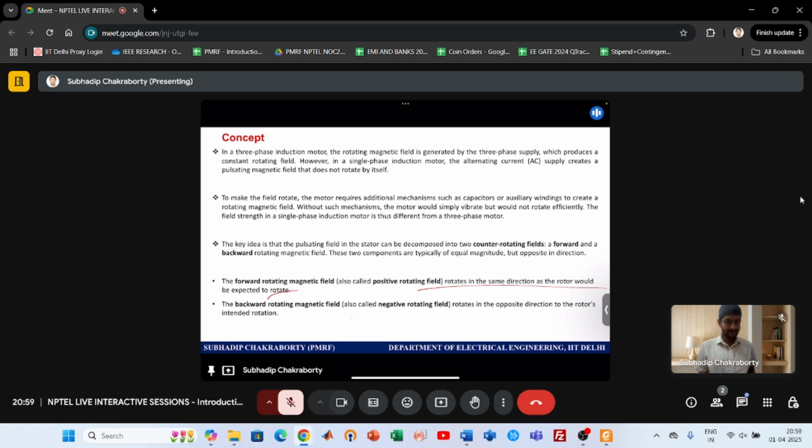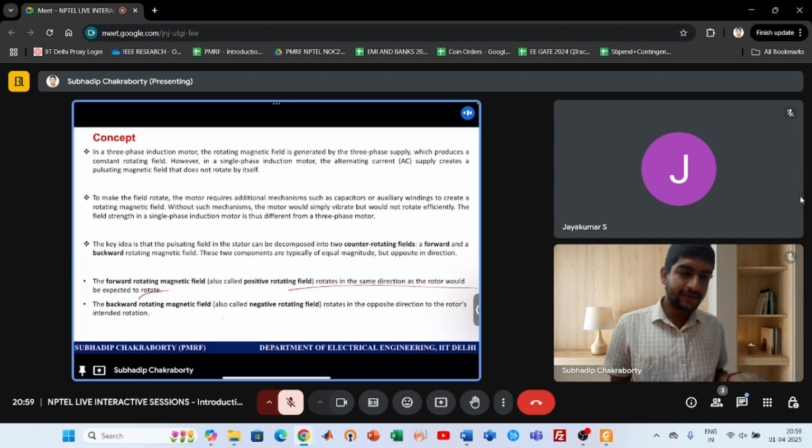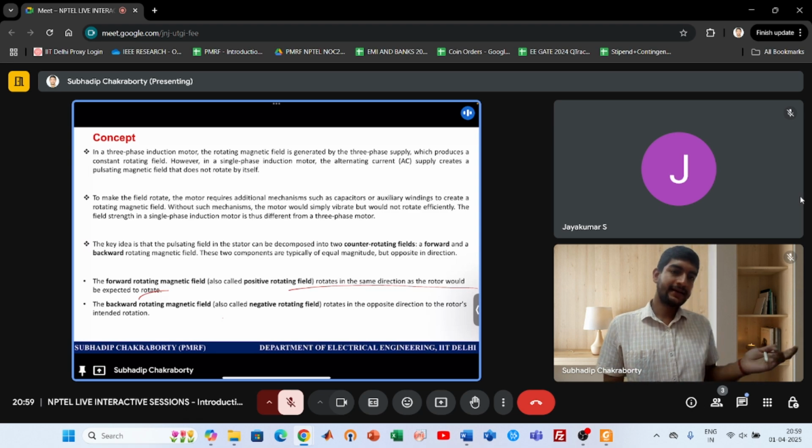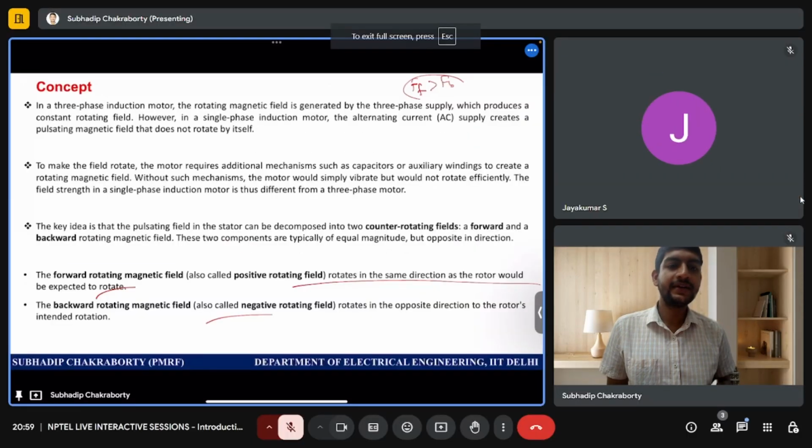To actually rotate the coil, rotate the rotor, to give some form of field by some phase displacement. So the capacitor we use actually creates a displacement between the two fields, and then once that starts, some speed comes, then I will prove or show you that the forward field strength is more than the backward field strength, and we get a smooth torque.